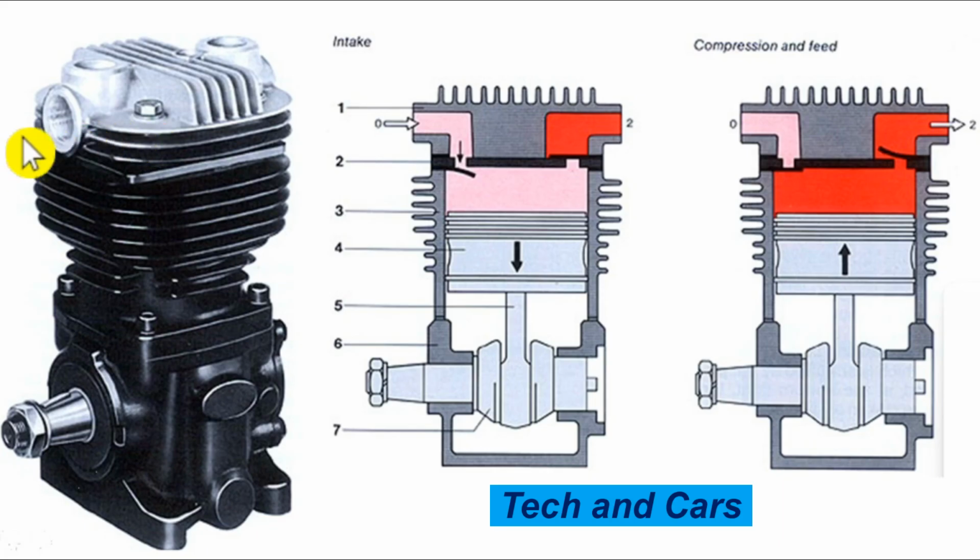And the compressor breathes in air, as we have discussed. It will breathe in air and breathe out air. Now, if the air filter is not correct, or if the air filter on its intake line is clogged, or if it is missing, dirt and dust can enter this. If dirt and debris, anything that can get in here, is sucked into the system, this will have an abrasive effect and cause rapid wear on the compressor itself. So dust, any type of dirt that gets sucked into the system will accelerate wear internally. So always make sure that your air compressor is getting filtered air.